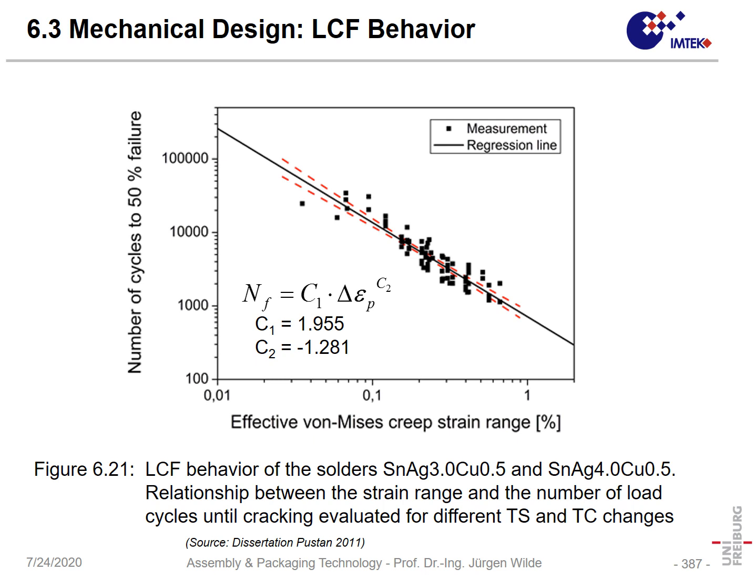So here, let's have a look. That was our measurement. In the end, for all of the measurements, under different conditions, the number of cycles to failure was analyzed, and it was plotted against the plastic strain range, which we got from simulations. And in that way, we get a lifetime curve. That's a Manson-Coffin curve.